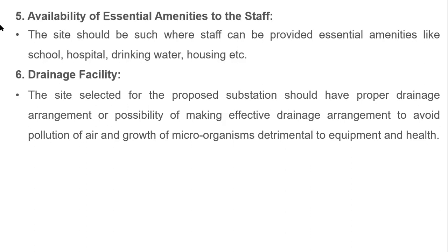First of all, what is meant by a substation? A substation means a group of equipment designed for step up, step down, AC to DC conversion and frequency changes. All the equipment installed together is called a substation. Normally there are different types of substations, depending upon the service and the constructional features, and they are divided into various types.